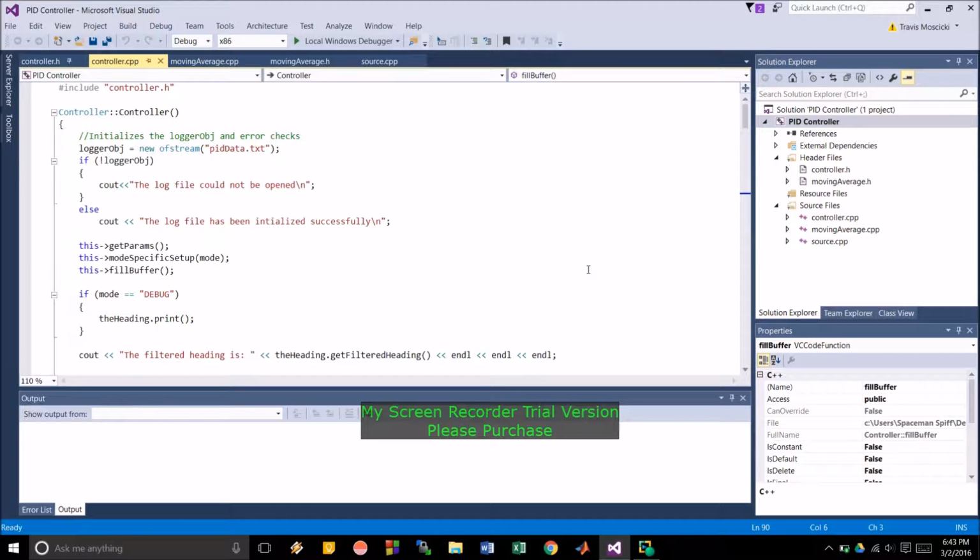The reason why I bring this up is we're going to implement a low-pass filter on our PID controller. It's a moving average filter, is the name of that variety. So the next thing that I want to talk about is what a P looks like, what a PI looks like, and what a PID looks like, the frequency response of the system.